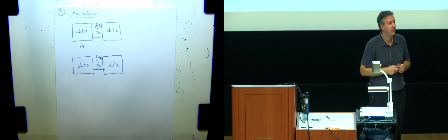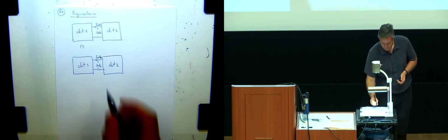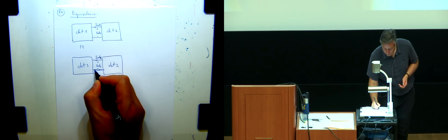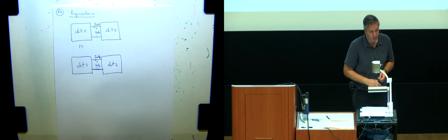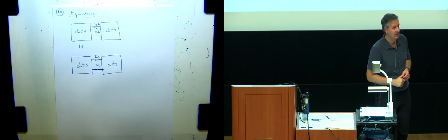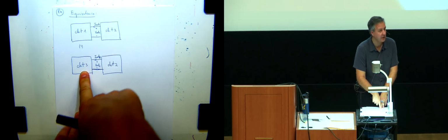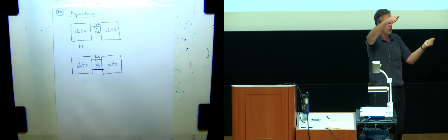What about the bottom wire? Current through the bottom wire. Oh, great question. The question is, what's the current through the bottom wire? Well, the answer is in KCL. If I treat this whole circuit as one big element, it has two terminals.